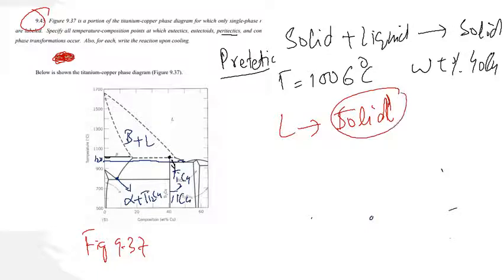We have to look at this melting point because it says congruent phase transformation, so it occurs congruently. If we look at the diagram, this is the liquid and it converts to beta plus liquid, so it is not a point of concern. Here it converts to a solid, it is not a point of concern.